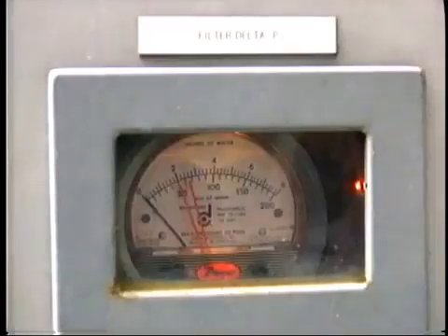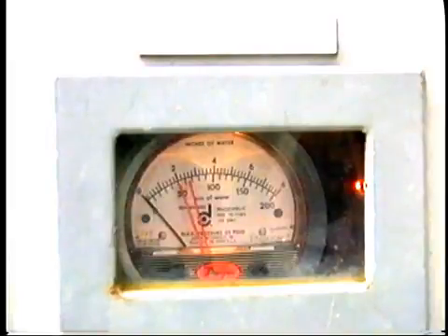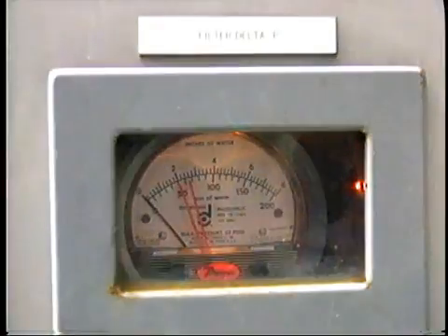As we can see, this system is self-contained and requires no attention from the operator other than to ensure that the filters are clean, thus allowing sufficient air to pass. The pressure drop across the filter will indicate when it needs to be replaced. On standby or peaking units, this task can easily be performed when the unit is out of service. However, on continuously operated base load units, automatic continuous filter cleaning is usually installed.